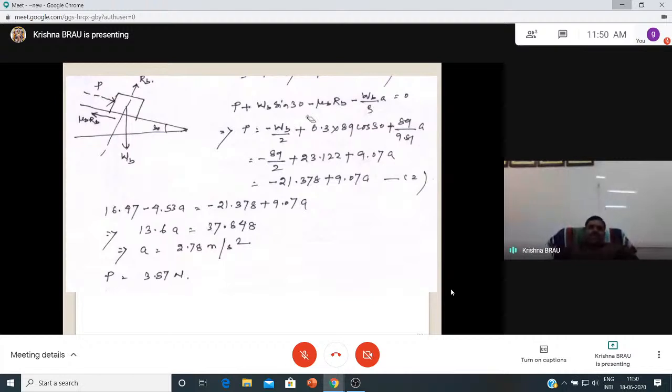See, this is how any type of problem can be solved. Either Newton's law or D'Alembert, both are force equations only, no difference. But the only thing is, in one problem we are solving by Newton's law considering the dynamic condition. D'Alembert's principle we are applying, we are converting a dynamic problem into a static problem. That equilibrium we are calling the dynamic equilibrium. And unknowns can be determined.